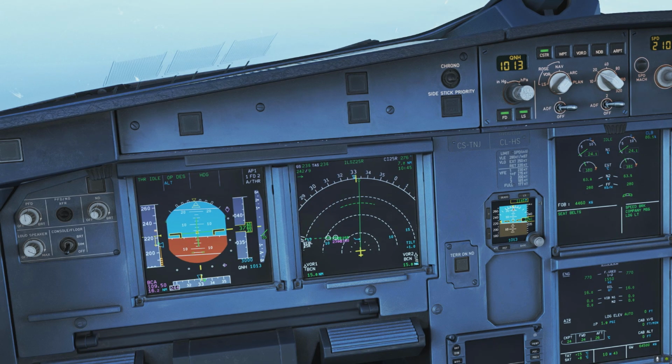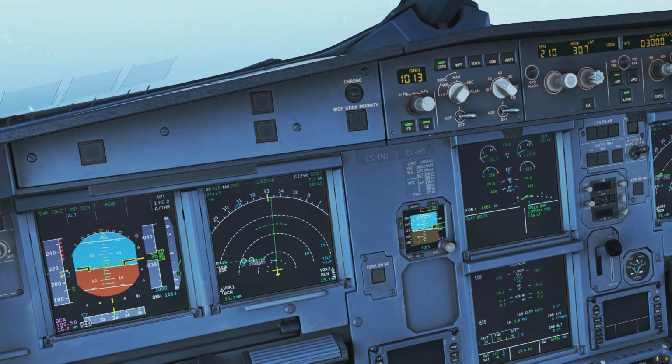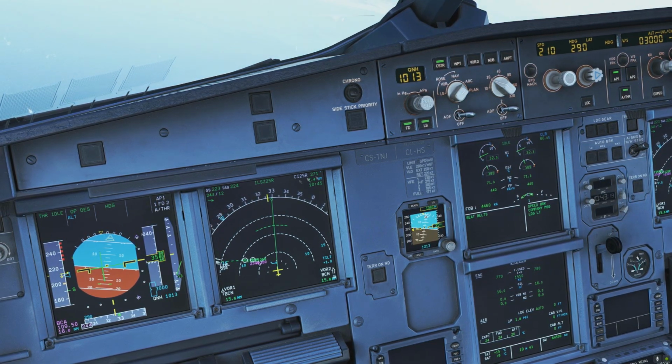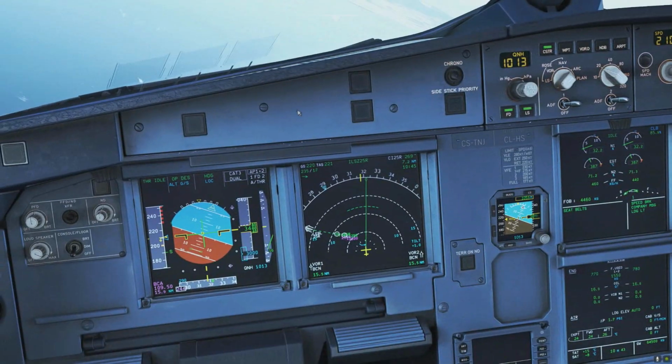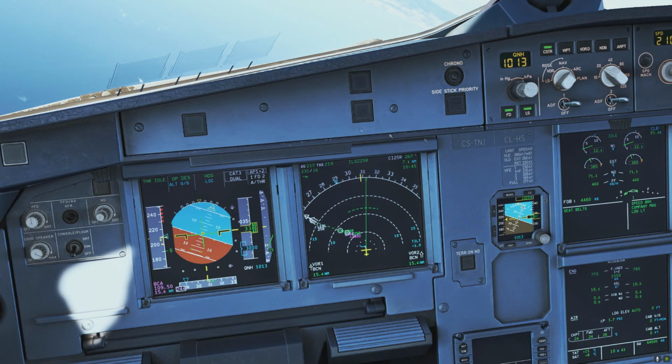We're now below VFE next, so flaps 1. And now they tell us turn left heading, let's call it 290, and we are cleared for the ILS. So we arm the ILS. Glide slope blue, loc blue, CAT 3 dual, autopilot 1 and 2.